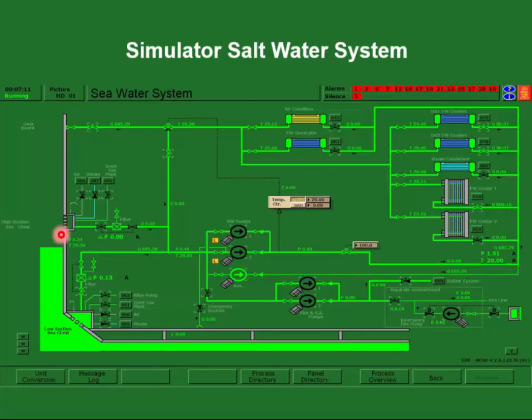On a tanker such as this, you'll change from low suction to high suction depending upon loading condition. In other words, you're on the low suction when the vessel is unloaded and high suction when the vessel is loaded, and you will change these from the one to the other as the loading condition changes at either the discharge or loading port.